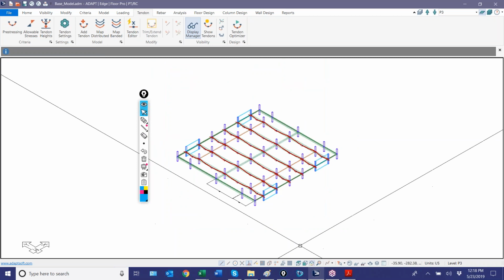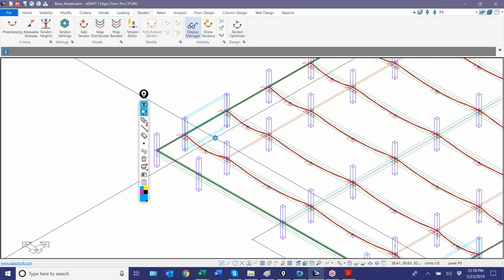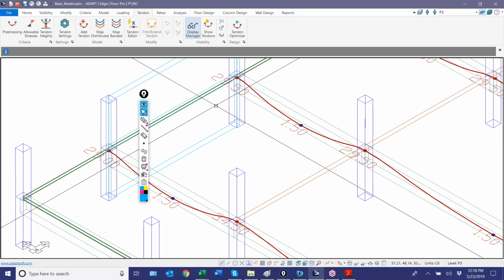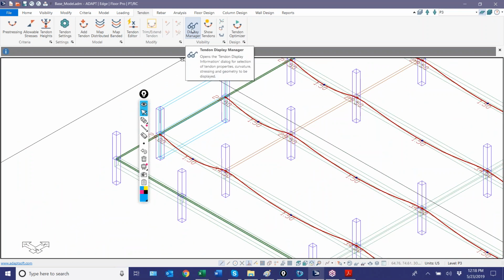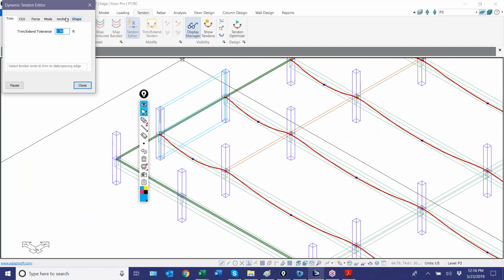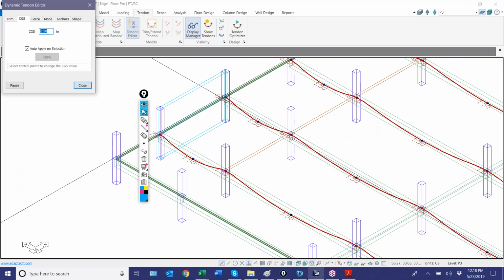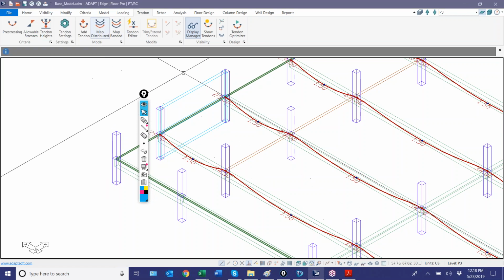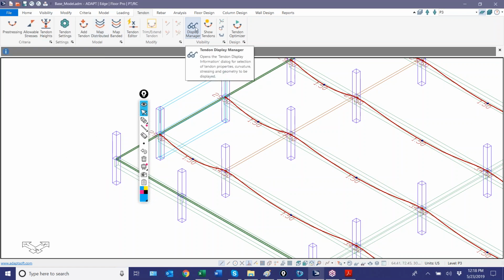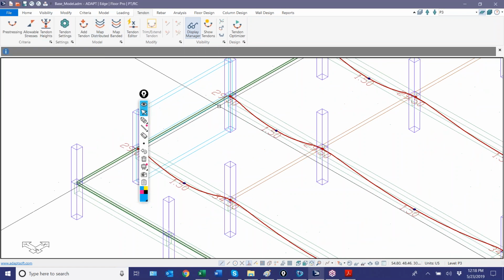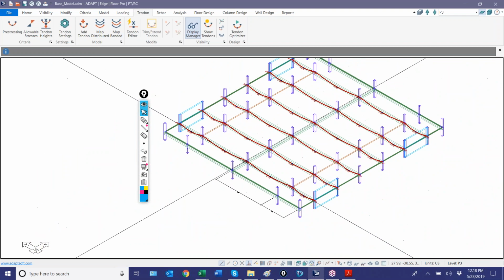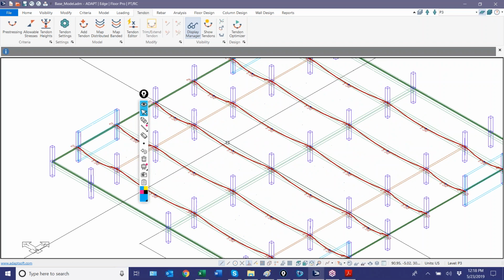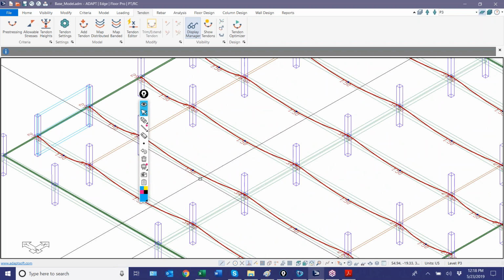Okay, going back to our view, just to see what this is looking like. Notice again, I'm referencing now from the display manager showing the control points. If I go out of tendon editor, notice that this says 6.5, 1.5, 6.5. If I close that and I have the display manager on, which is currently showing control points, this actually changes from bottom up to 29.5. So that automatically will update the CG based on the view you're looking at the tendons in.